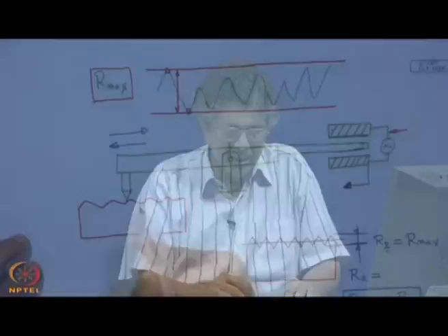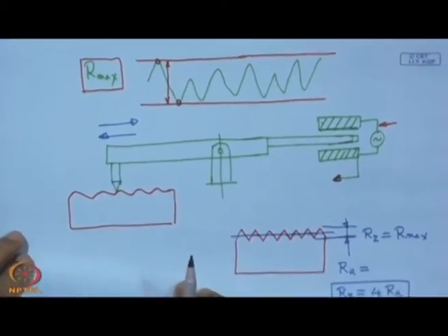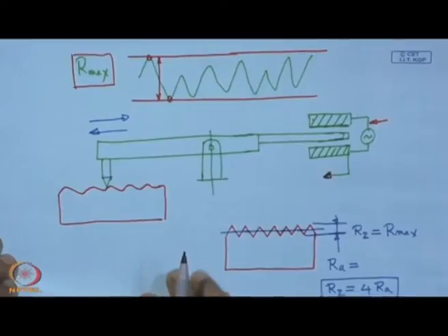If this surface has micro detailing at the micrometer or nanometer level, with many sharp corners, the stylus may be limited in recording all that micro detail, and those will be rounded off. However, for comparison of two surfaces, just for assessing whether it is a rough surface or a smooth surface with reasonable accuracy and quantification, these machines are quite convenient and reliable for all sorts of engineering applications.